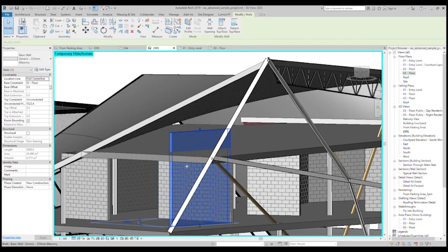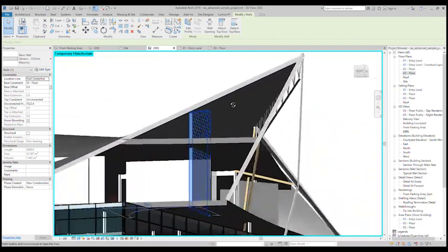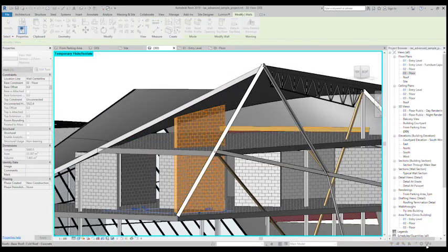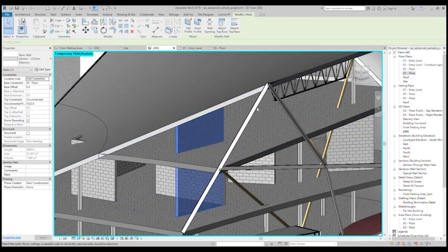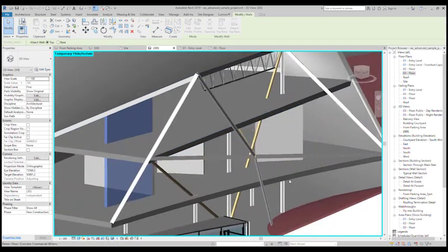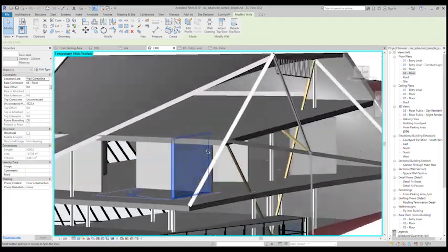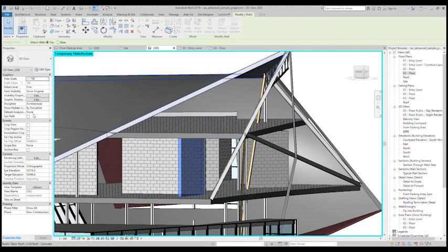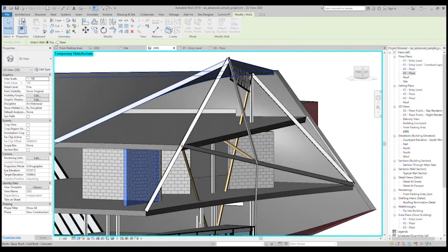So once you click on the wall, I can click attach to roof, and there, that wall is now attaching to that roof. Attach to floor. Oops, sorry. You can actually attach it to beams as well, but we're not going to do it. Oh no, you can't. I thought you could. You can attach it to floors. So now I've moved it down to that floor. Okay. And again, like any other thing, like a column, you can attach its base as well.